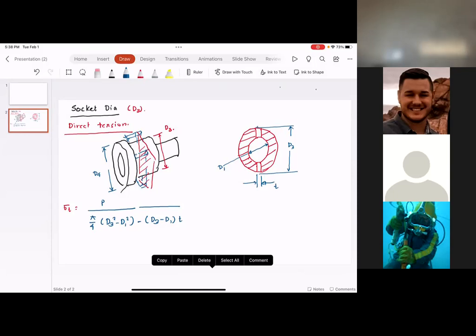So what this is telling us is even though the cotter has failed in bending, it has deformed, but that's okay, because what we want is for that joint to remain rigid. So slight deformation is okay. So even if your cotter is failing in bending, usually it would fail in bending. Just say that this is a fail-safe design. The cotter bending failure is because of yielding and not because of fracture.